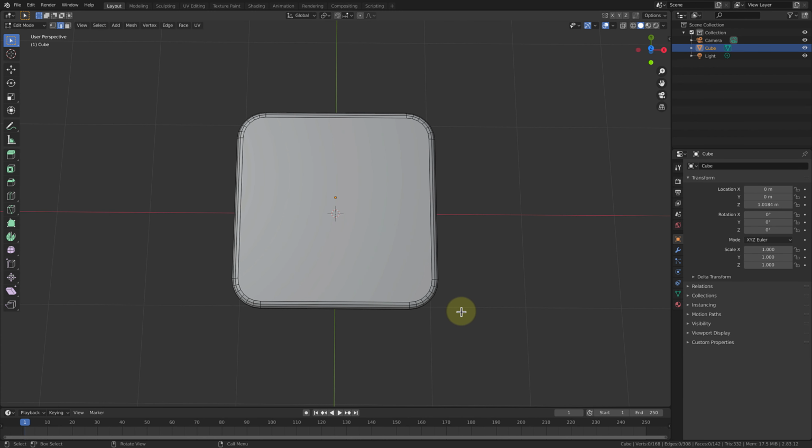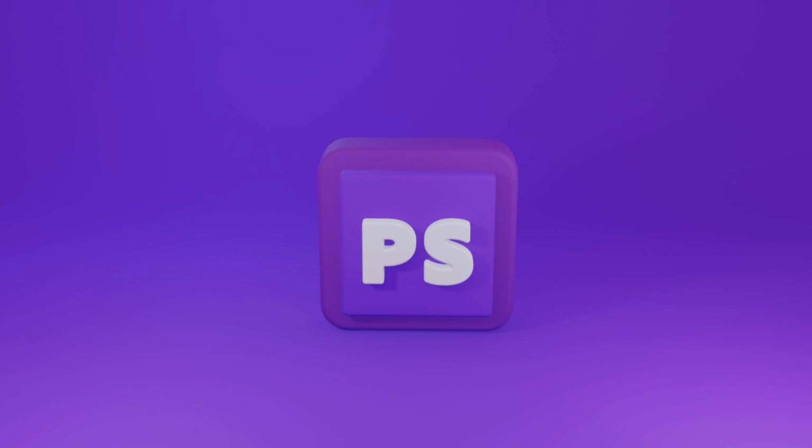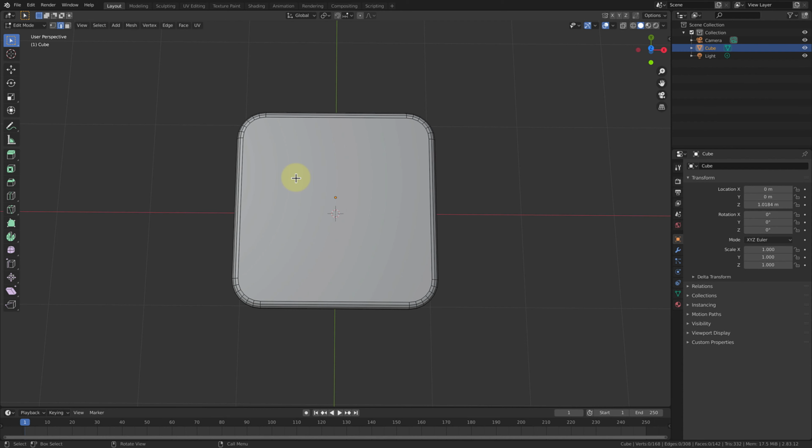Now that I have it beveled, the next thing I want to do is extrude this face inward, so I can create another similar square. If you take a look at the photo, I want to create this square. So I select this face. Tap 3 to select face, and then use inset face, which is basically extrude inward. Instead of using the tool, I can hold down I, the shortcut key, and I think this is a good size.